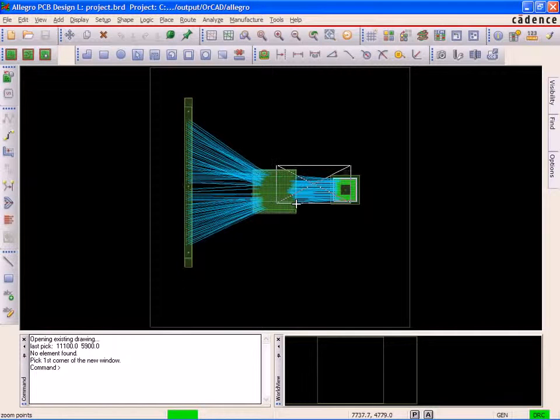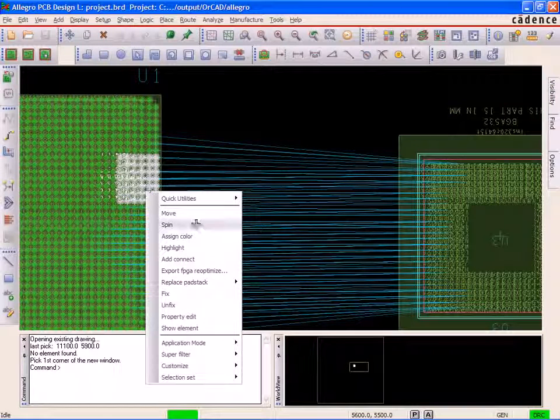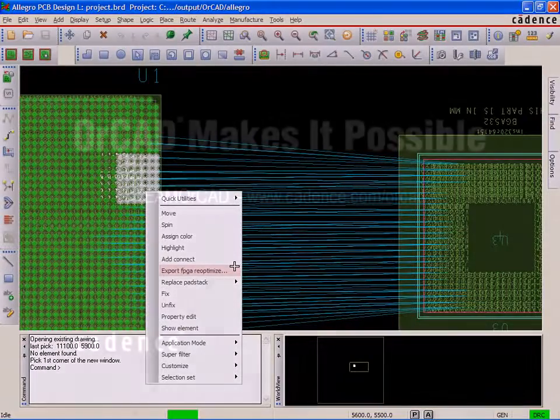Swap requests can be made for multiple pins or for 2 pins at a time. Those swap requests are then fed back to FSP for validation and execution. Using FSP to validate and perform the actual pin swaps ensures that the FPGA DRCs are adhered to and that the FPGA design will continue to operate correctly.